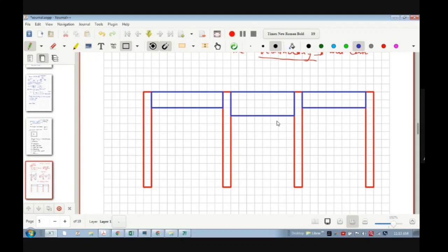Aesthetically लग रहा है अच्छा, आपको नहीं लग रहा ना? Because this bottom is not in one line. And let's say this span is more. If you feel that 750 I require structurally, I cannot manage without 750, so there is a choice that you can increase these sizes. Okay. तो ऐसे कर सकते हैं हम, all 750 करो. अगर आपको structurally problem है तो then make it 750 all. And then if you do this, then it will look good, because the bottom line of the beam is same in one line, and it will give a good aesthetic feeling.